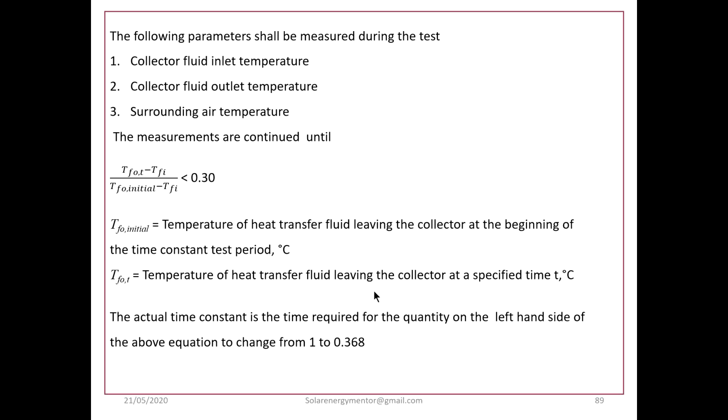For example, we will take an example. I have already said that ambient temperature is 27 degrees Celsius and TFI we are maintaining at 28 degrees Celsius. Suppose TFO, the collector fluid outlet temperature, at the first instant measured is 32 degrees Celsius. Now 32 degrees Celsius minus 28 degrees Celsius is 4. After 5 minutes, the collector fluid outlet temperature naturally reduces because the collector is covered. So suppose it is reduced to 29.5.